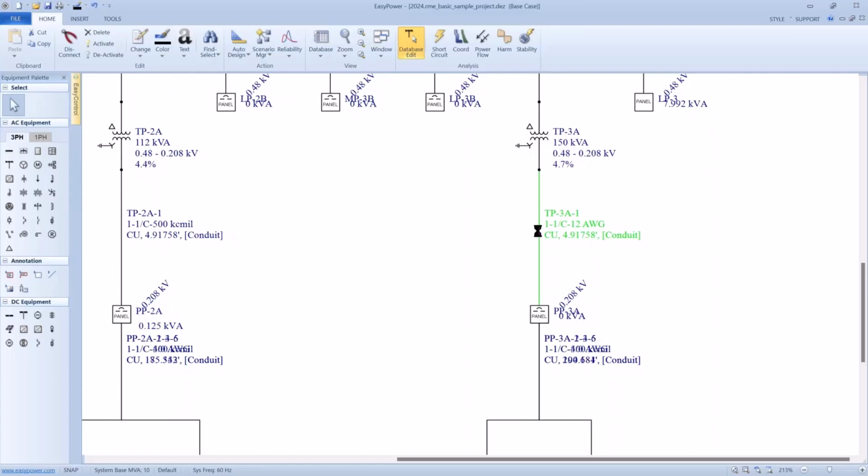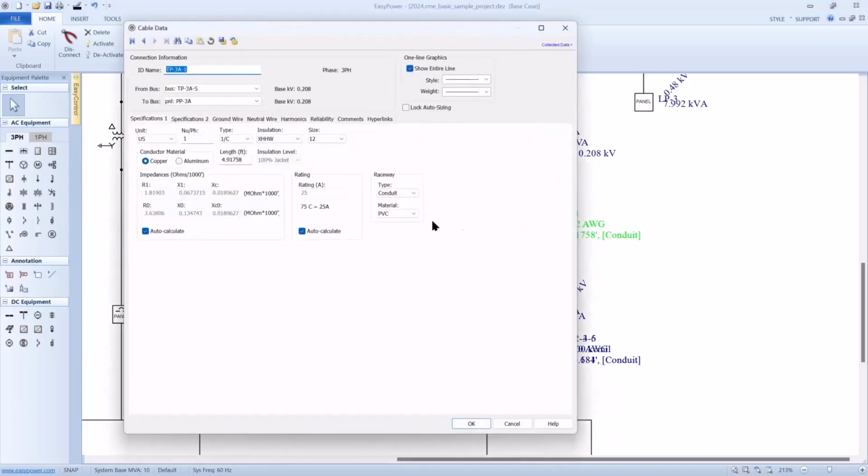And so it's a matter of dropping quite a bit more than it was rated for. So let's set this up as a 2 conductor per phase, size 250. I think I want 600 amps. So now again, this is not a recommended way to design stuff. I'm just trying to show the advantage of the tool.